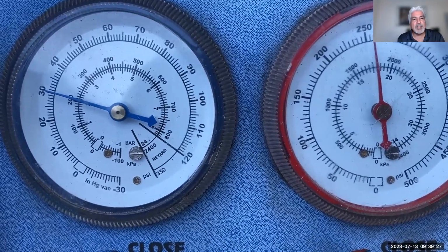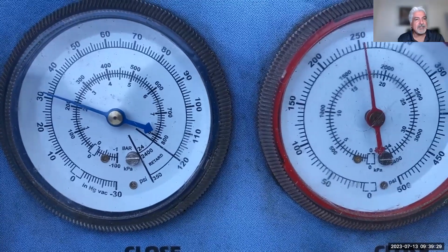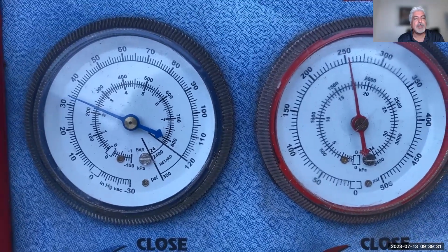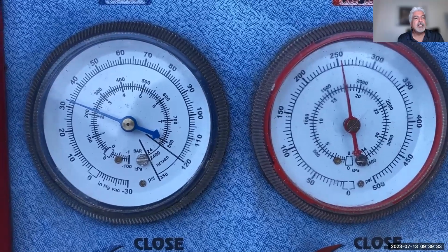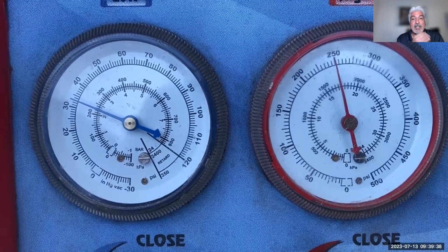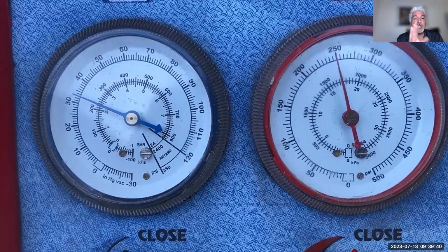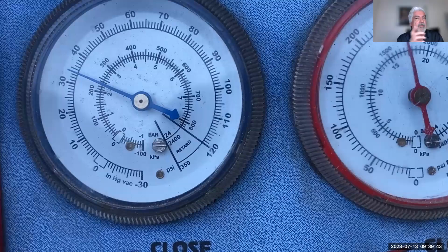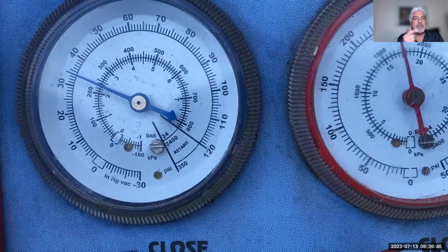If I'm working on a TXV and it's fixed and stays fixed and never changes no matter what I do with the RPM, when I spin the compressor faster, then I could have a stuck thermostatic expansion valve. Now I'll tell you a trick that I do on some stuck TXVs. I've been known to unstick them. I'll have my water hose ready with cold water, and I will spray the front of the vehicle, the condenser, with cold water, because it's pretty cold out here. And I'll spray it across.